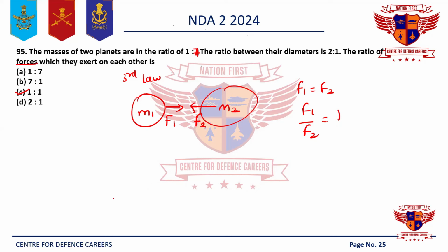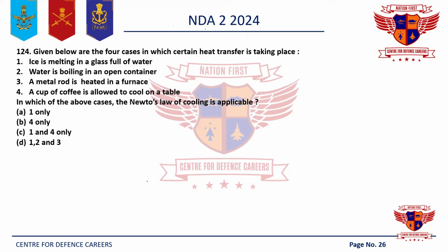Now moving on to the next question. Given below are the 4 cases in which certain heat transfer is taking place. In which of the above cases is Newton's law of cooling applicable? Ice is melting in a glass full of water. Here nothing is cooling, the ice is actually heating up. That is why it is converting into water. So here Newton's law of cooling will not be applicable.